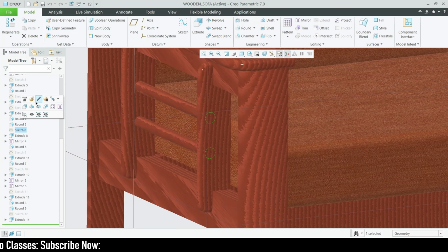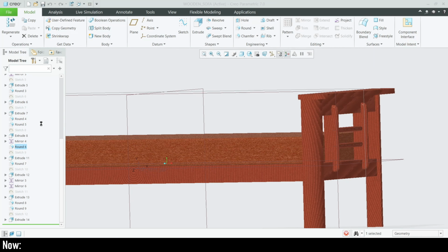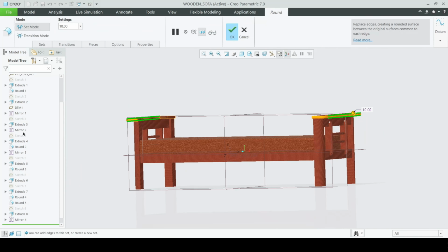Okay, good. And we have to extrude that up to the next surface of this. So this up to the surface. I think we have done everything. So we have to mirror it on the other side. You can see everything we have mirrored, and here I'm just adding a rounded value for this corner edge. You can see the corner. So full round feature of a value 10.